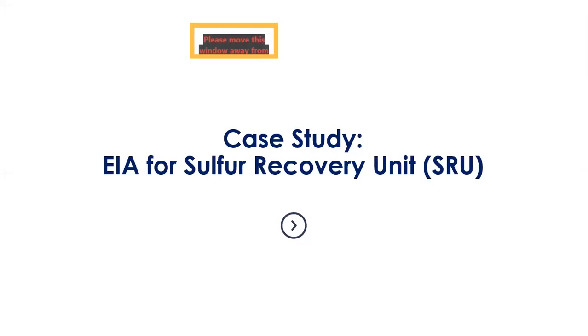Is it possible to carry out EIA without going through the IEE stage? Yes, as I mentioned before, in some countries we call it IEE, initial environmental examination. In some countries, it's EIA. In some countries, it's only the management plan that they require. So it depends on the project. If the regulatory authority determines that this kind of project only requires IEE, then initial environmental examination will only be carried out, with no need for a detailed environmental impact assessment. But if the regulatory authority determines that the project requires a detailed environmental impact assessment instead of initial environmental examination, then the project proponent or the consultant has to carry out the detailed environmental impact assessment.